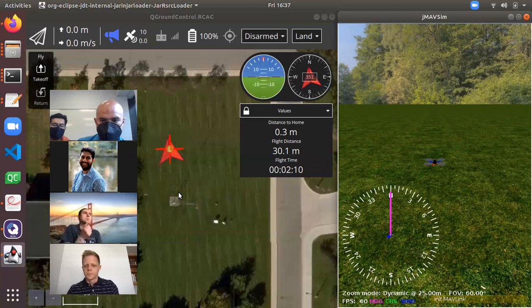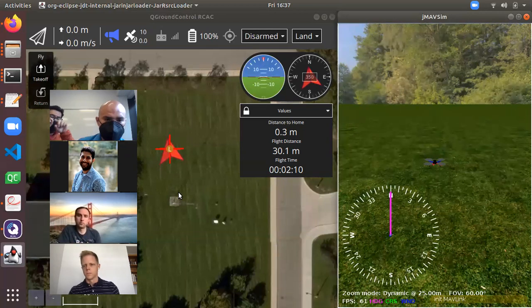A slightly different way of saying it is that at each point, if you give it an initial point and then give a final point far away, that's a huge error. The controller reacts to the errors, and a giant error is going to produce a giant response. Instead, if you populate this line with small increments, at each point your error becomes small, so your controller response is also smaller. That's exactly what you just said, but slightly different.